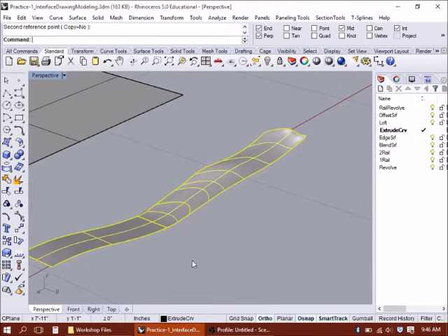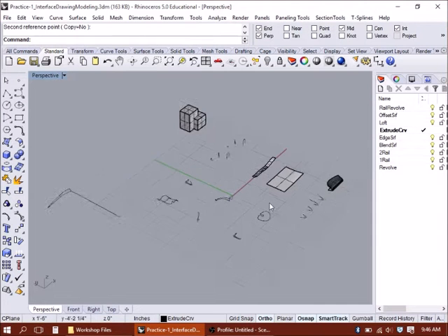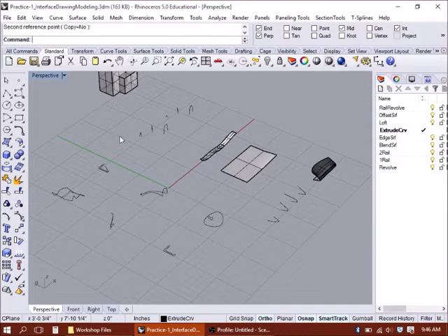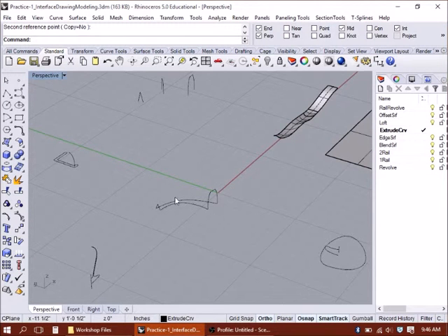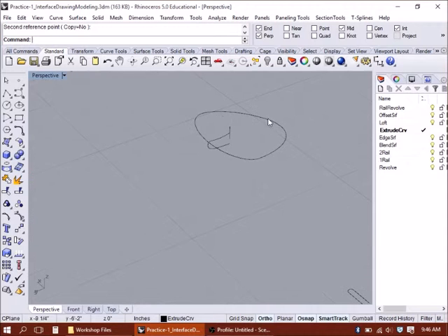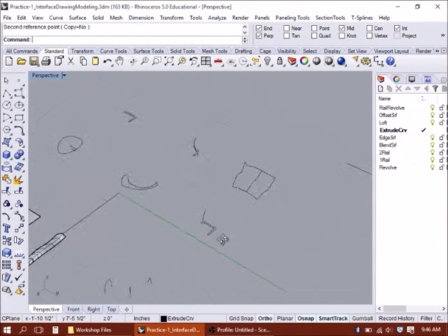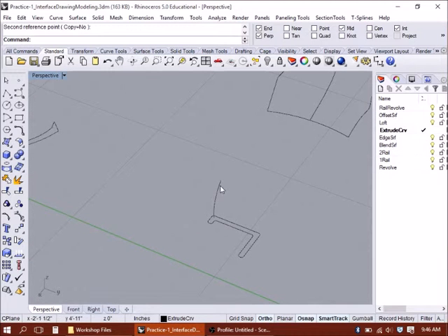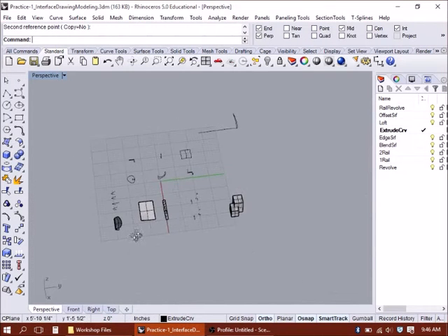Okay, so just a few other tools that might be useful as you guys are working through this. Of course, things to keep in mind as we get through this project and on to the next. This is a file. I'll upload this for you guys. There are a series of different little practice vignettes here. Different ways to loft, sweep two rails with two profiles, the rotate tool. Here we have a rotate and a rail rotate, so that can be interesting. Extrude along a curve: instead of just extruding straight, we can extrude something along a curve. That's something I might go over a little bit later, as a series of quick little tutorials.